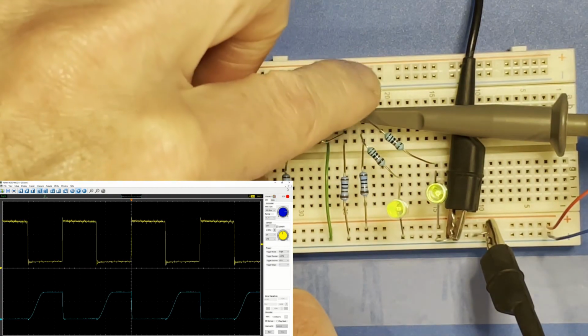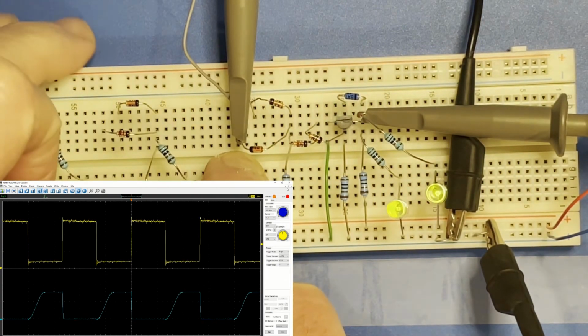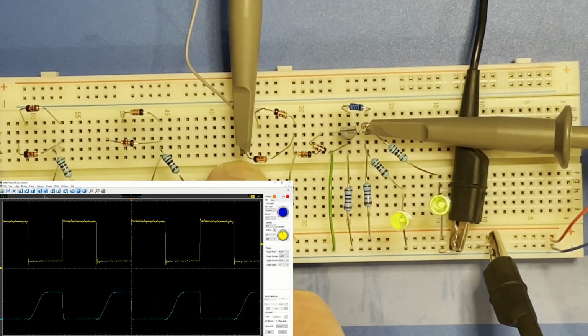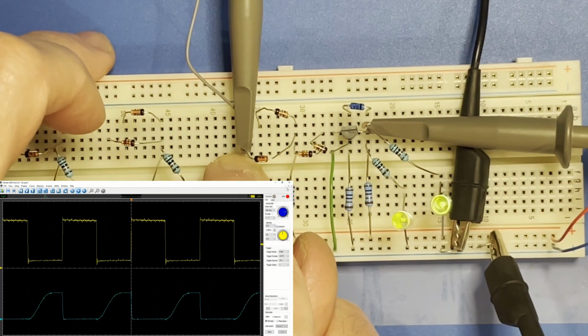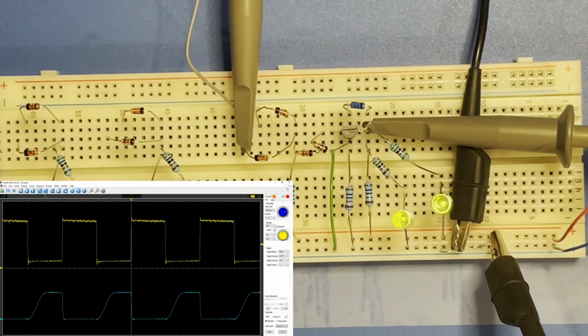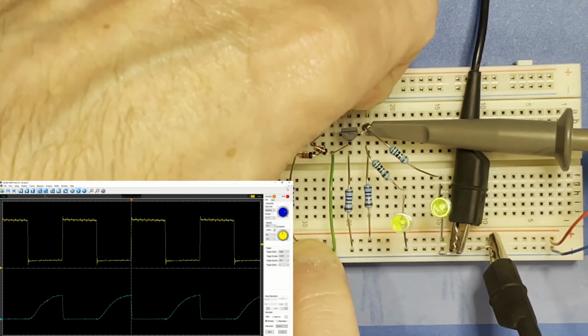So by adding the diode, that converts the transistor to a Schottky transistor, and that was one of the big, almost revolutionary changes in early logic ICs in the 74 series, when 74LS, which is low power Schottky, that's what the LS stands for, was introduced, as all the internal resistor values could be much higher and the operating current much lower, because it didn't need high current loads to help the transistors turn off so quickly. It's just a very simple way of vastly speeding up a transistor.